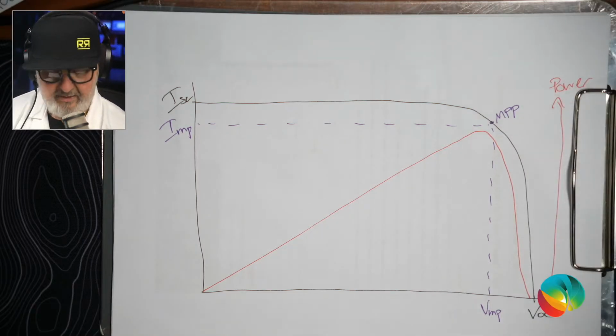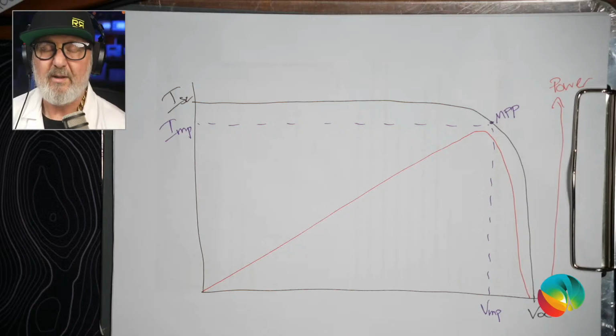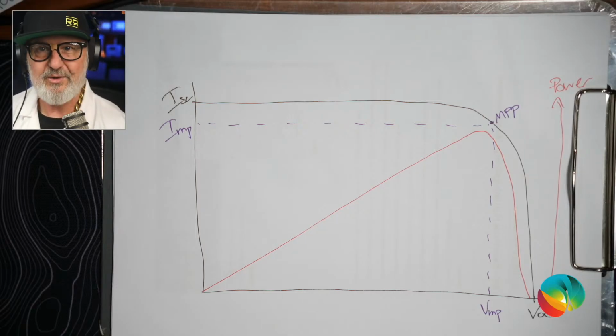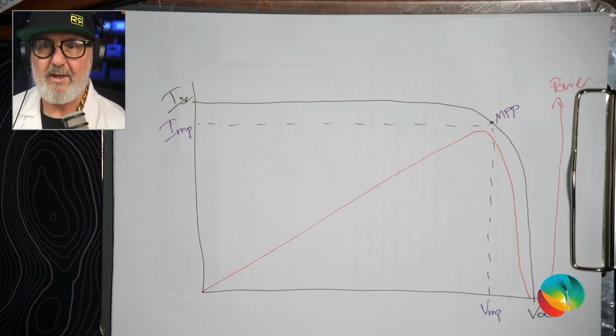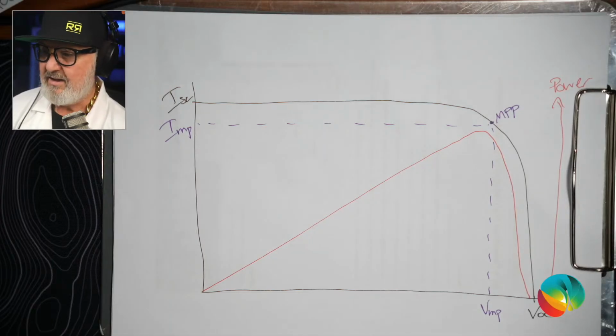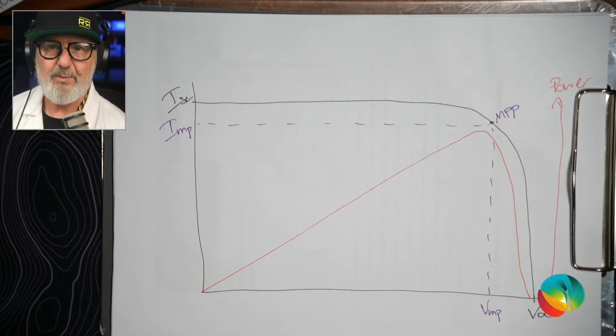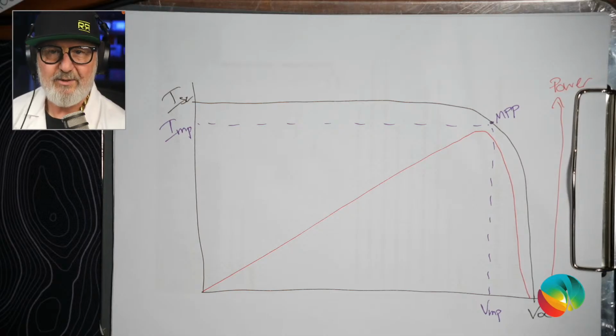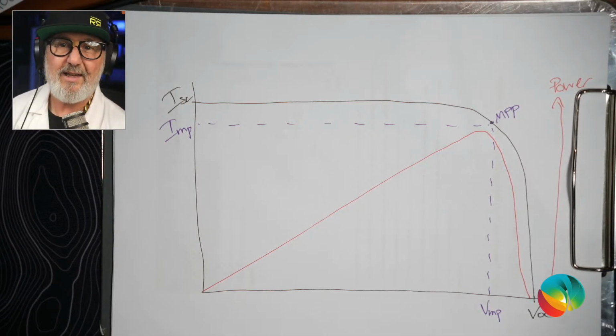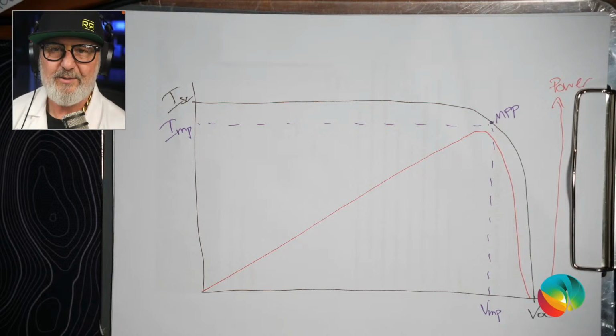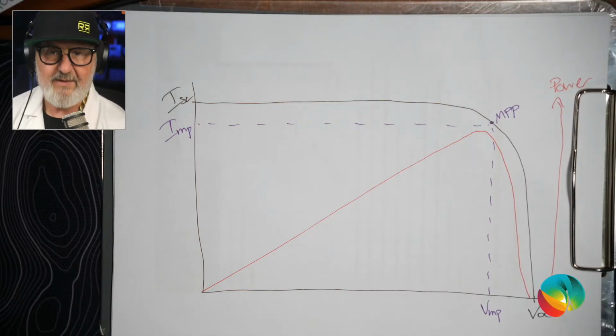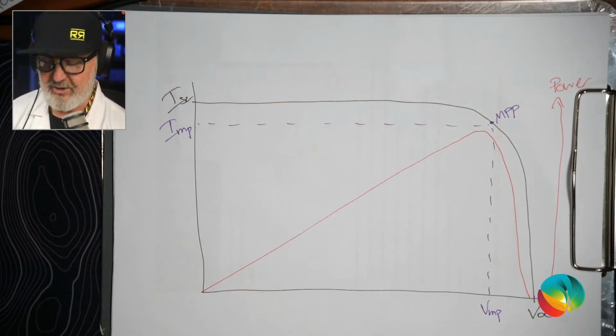Okay, all very well. But a double peak MPP is when you've got some perturbance in terms of the panel's performance in a string. Let's say you've got 6 panels, and as Charles is doing today, he's putting a chimney right through the middle of his array, so it's going to cast some shade on one of those panels, or 2 of them maybe, depending on where he puts it. That panel is going to be suppressed a little bit in its production. It may even go into complete bypass, which would be a shame.